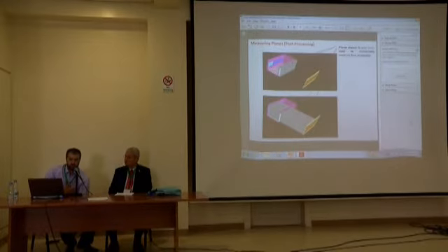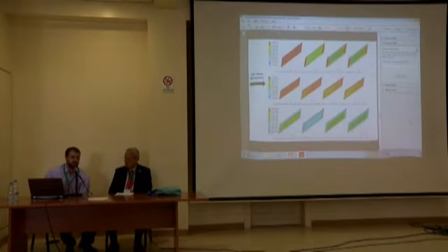In post-processing, you can have many options, either by defining several probe points or measuring planes in order to visualize how the flow is changing, and the flow parameters, properties, temperature, species distribution, etc. The plane shown in gray color is used to numerically measure some flow properties. I will not go into deep analysis of the results. Look at the air flow direction in this black arrow. The first figure shows a plane before the coil and planes after the coil, and there you see the change of temperature, of course, due to the heat transfer happening.